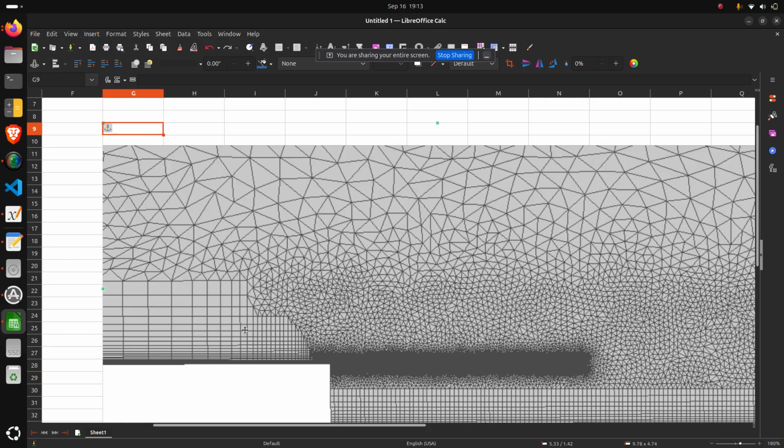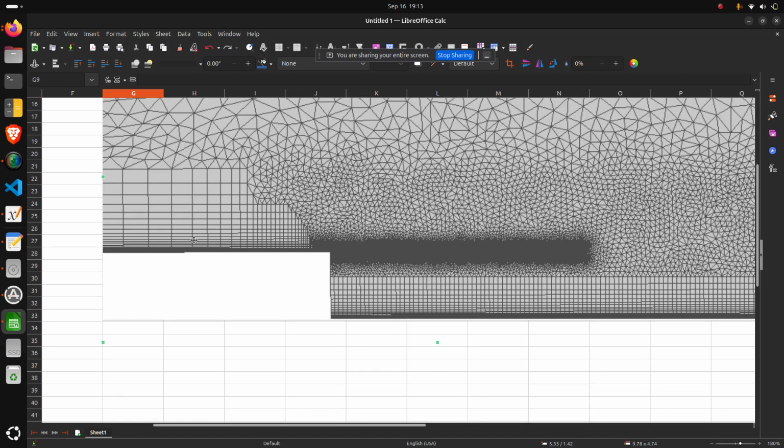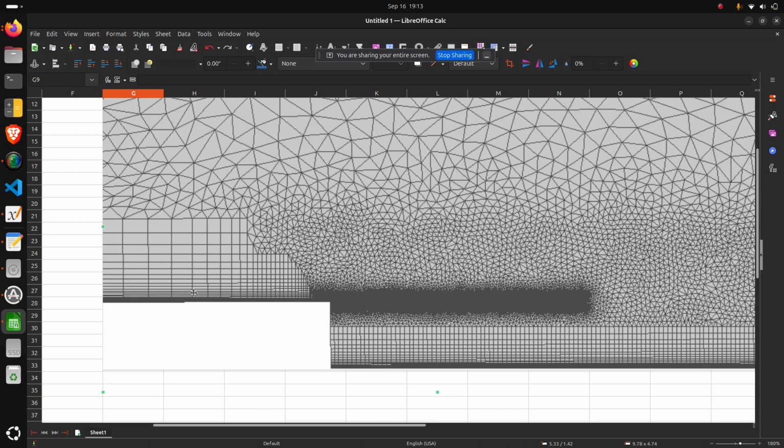But in this region we see quite definitive grid lines in the x and in the y direction. So we can easily classify them into i equal to 1, 2, 3, 4 and j equal to 1, 2, 3, 4 like this. This is a flow over a step, this is a wall, and very close to the wall the grid spacing is very fine, right?